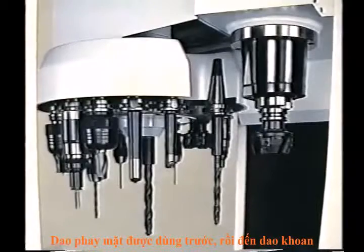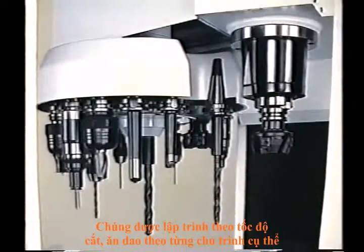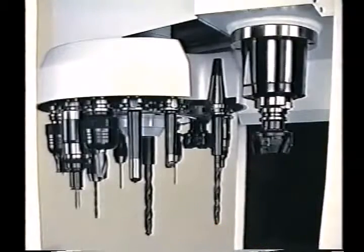And what we have in the spindle right here is a face mill that could be used to face mill the part we saw a little earlier. We also have a number of drills here in our tool changer. We have a number of boring bars. We have a couple of taps, each of which requires for us to figure out the proper RPM, proper feed rate, of course the programming sequence to do that particular kind of operation.